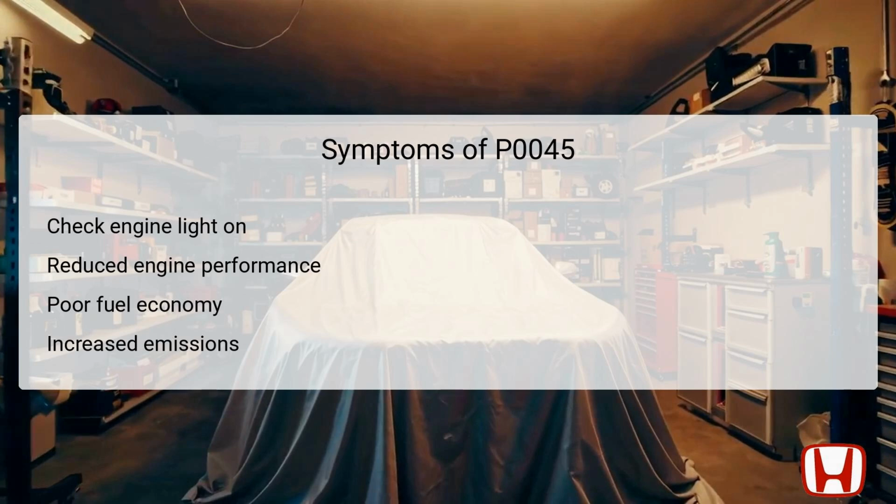Poor fuel economy is another potential symptom, as an ineffective wastegate can lead to excessive fuel consumption. Additionally, increased emissions may occur due to incorrect air-fuel ratios caused by improper turbocharger operation. Thus, monitoring for these symptoms during troubleshooting can help streamline the diagnostic process, allowing for quicker resolutions.